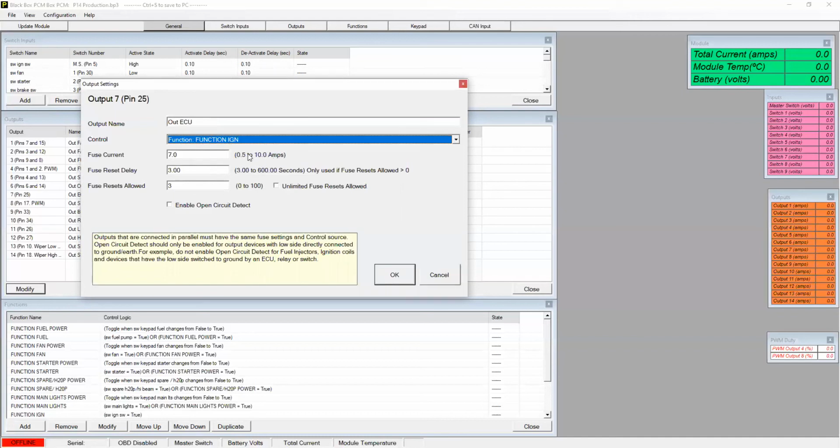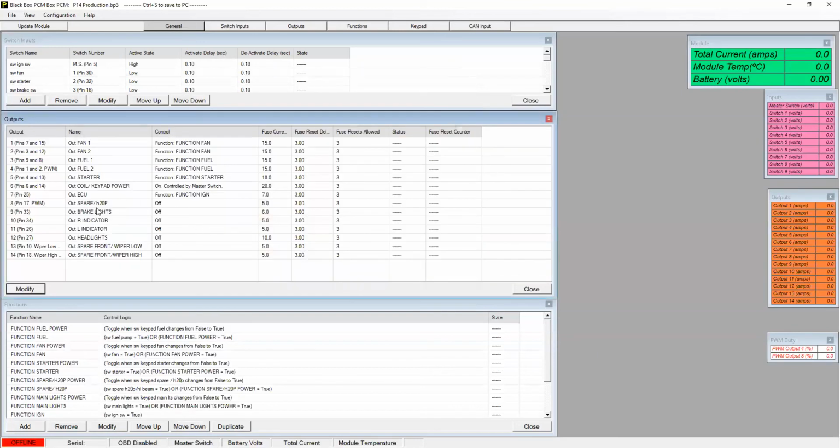And when you're on the dyno, if you have to make split-second changes, you'd have to break up some outputs and change some stuff if you see that your duty cycle on your injectors is going way up, and then it's drawing more amps, and it could even trigger a fault. So that's what you got to do, because I don't know if you guys are using 20 fuel injectors on one output, or if you got 4 in an ECU. Like, 4 injectors in an ECU is like nothing. You could have this number probably less than 7. So that's what I'm going to do there.